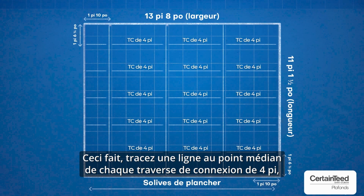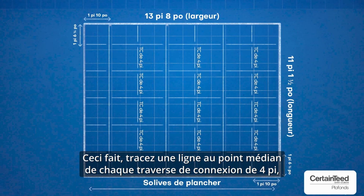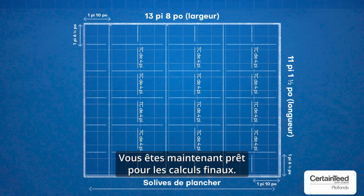Now that you have completed your 4 foot cross tee locations, draw a line at the midpoint of each 4 foot cross tee perpendicularly. This locates your 2 foot cross tees. You are now ready for your final calculations.